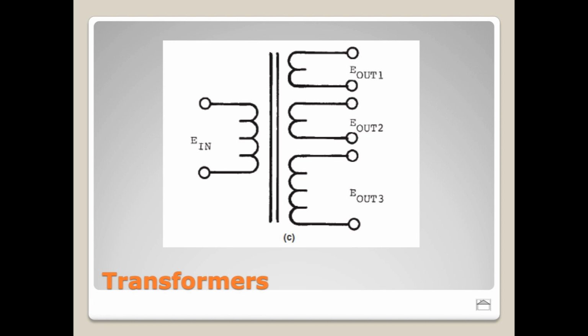Depending on whether we're dealing with preamp or power tubes, we're looking at maybe 230 volts all the way up to about 350 volts. And that's what actually allows the electrons to jump from one side to the other and actually make the vacuum tube function. So those two voltages need to be generated from a power supply in a tube device. And in this case, we actually have 3 different secondaries, so maybe this piece of equipment also needs an additional voltage. Maybe we're driving some relays, or we've got some other circuits that require a different voltage.